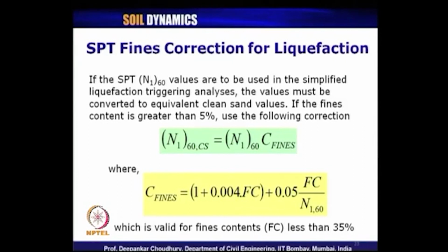If the amount of fines in the total soil, found while doing the sieve analysis or gradation study, is greater than 5%, then we need to apply this correction, which is called equivalent clean sand fines correction. This is the fines correction factor and the corrected value is N160 CS.